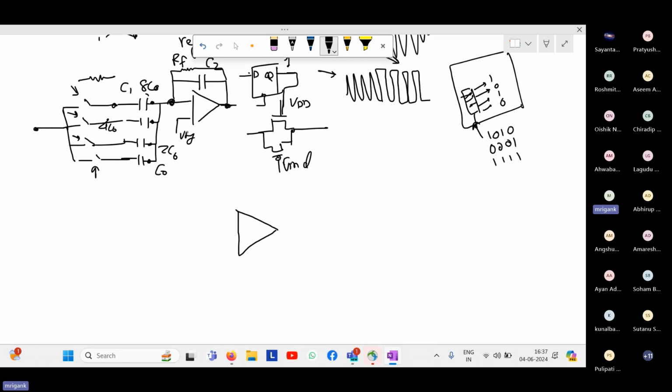As a result, the output DC level will be the same as VREF. So in the normal condition, the comparator will be getting an input signal very close to VREF. Fluctuation will be there, but it will be around VREF. But when the seizure appears, the fluctuations will start. So now, in this case, how do we decide the reference threshold? So this is the reference.